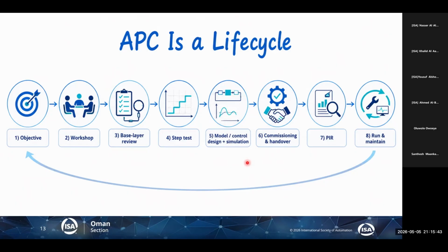And you have KPIs. You monitor the uptime. You monitor that each MV, every degree of freedom you have, is being used. Otherwise, why do you have a certain MV and it's not moving at all? Of course, the reason is very simple. The plant does change.